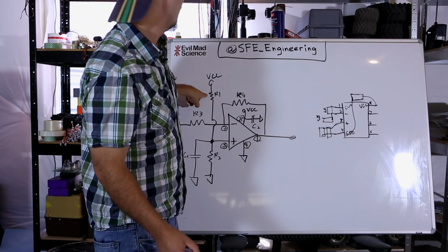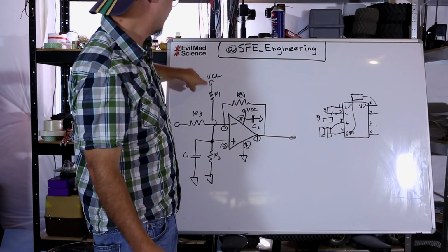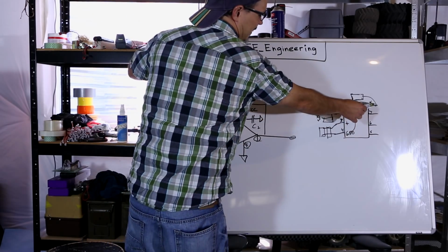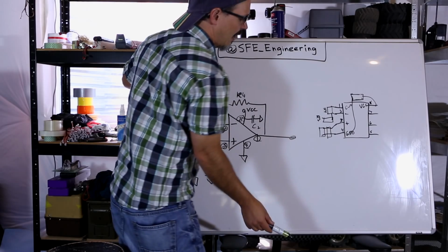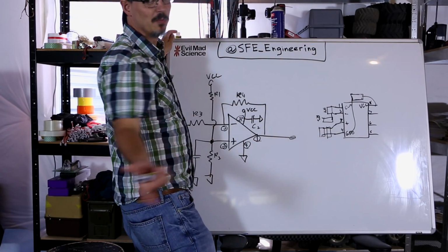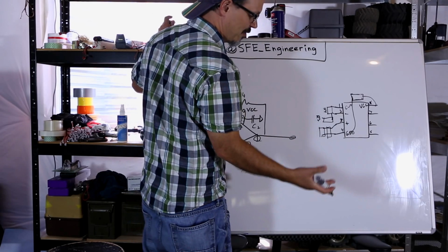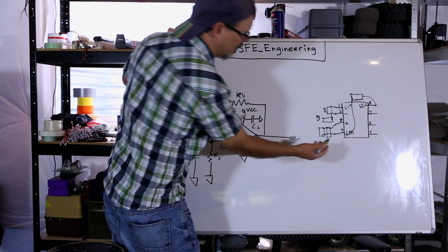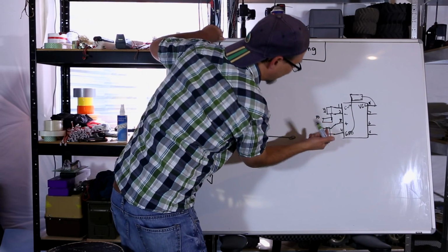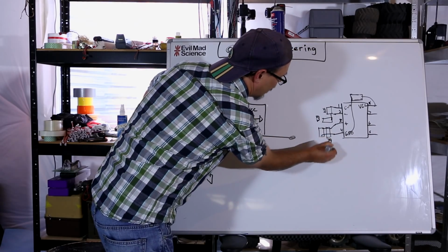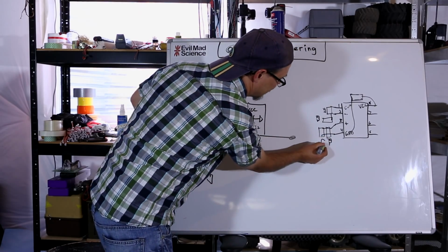Now there's this guy, R1, that goes from VCC to pin 3. Now, as you see, I've got VCC all the way over here. So I've got 2 points where I have to get VCC to, but I can try to minimize it, all right? Now, I know that it's got to go to the top of R2. I've done something wrong. Wait a minute. Sorry, there's my mistake. That's R3, not R2. This is R2. This is going to be C1.